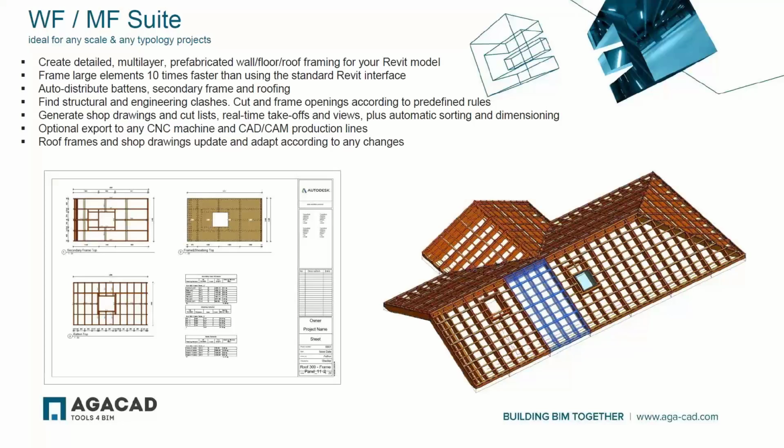Whether your elements are multi-framed or multi-layered, and most of the time they are, you're able to generate framing for all these separate layers, and provide sheeting, paneling, cladding, and various additional layers. This uses Revit families that come together with the tools, the configurations that you set up, the families that you load into the project, as well as the Revit model itself.